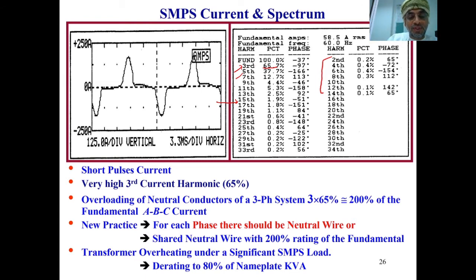It will overload the neutral conductor of a three-phase system. So we need to make sure that the neutral wire is really designed to carry this high current. It will also cause transformer overheating under a significant switch mode power supply load.